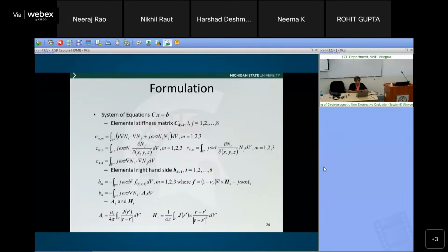Because see, in the eddy current problem that I'm looking at, suppose you just imagine I'm doing a raster scan. If the coil and the geometry were all integrated, at each position of the coil, it's a different finite element problem. I have to mesh the coil, I have to mesh the sample, I have to input the source and then do that. And now I'm decoupling it. That means now if the coil geometry has changed, from a pancake coil to a plus point coil, I have to go back and redo everything.